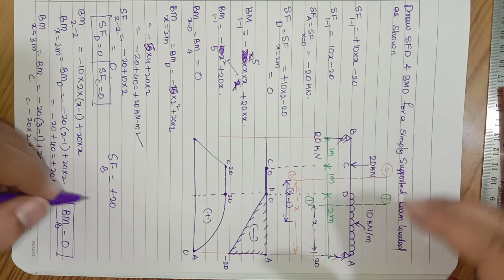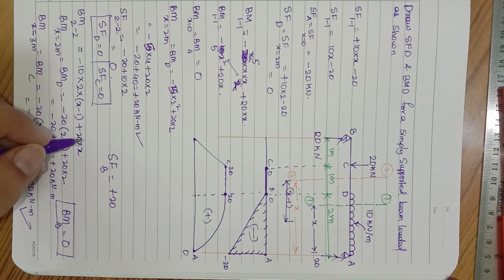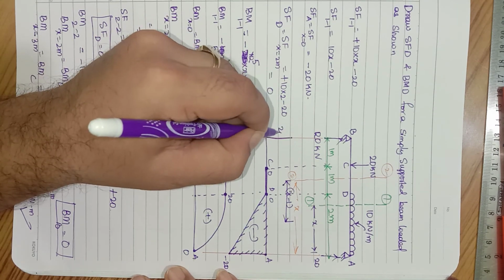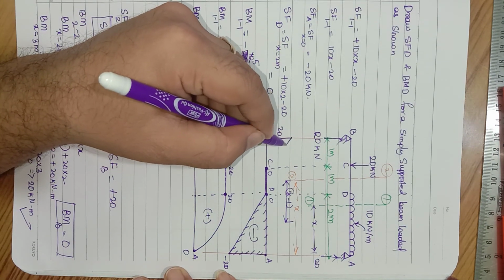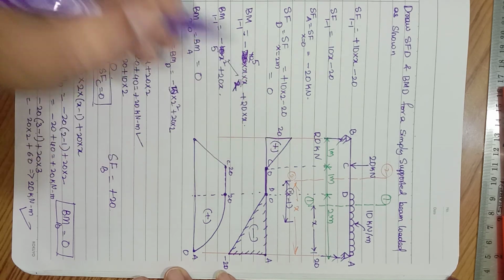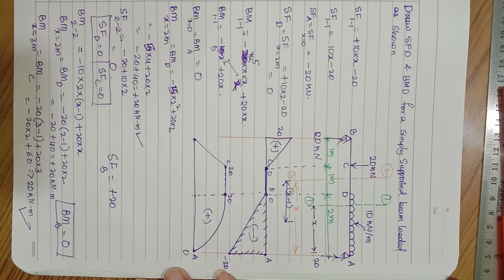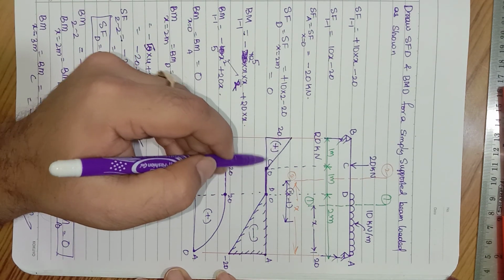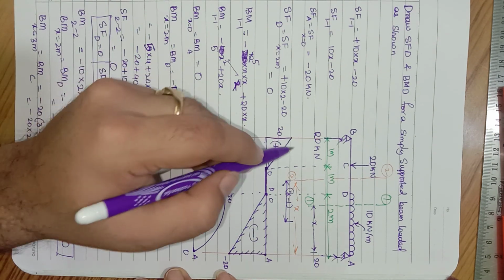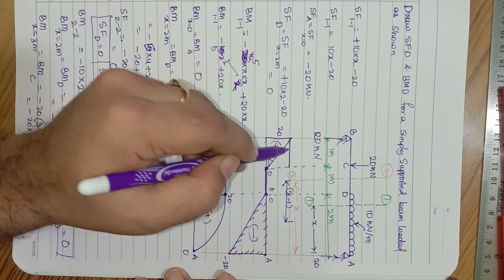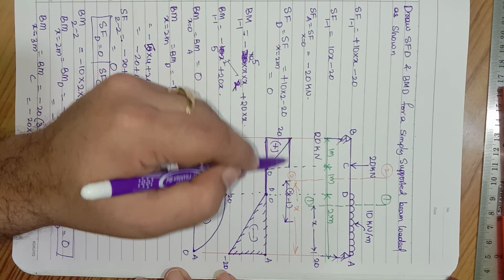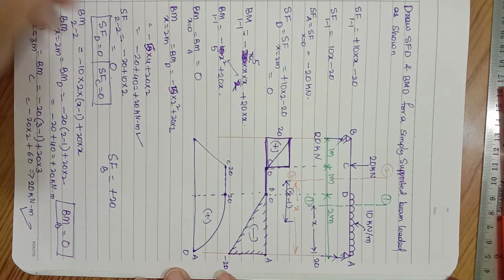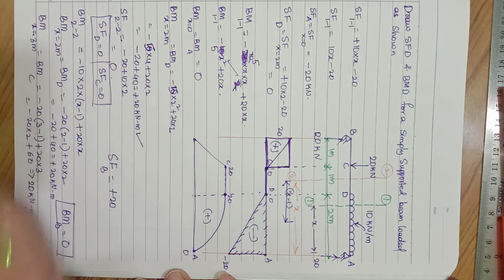If I consider towards the right side of the section, left side of the section. So obviously I'm marking plus 20 over here, this is plus 20, and the variation between these 2 points will be linear. So this should be taken as positive. But there is a small mistake here, right? Actually it will not be the triangle. As you can see, there are no other forces in between these two things, so it will be a line parallel to the baseline, up to here. So this is the correct one. This one should be here. It looks like a box. That's it. Thank you.